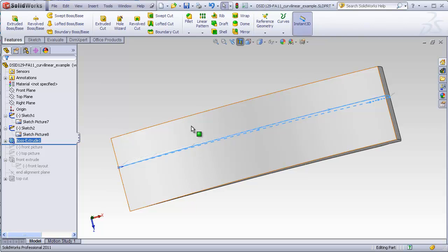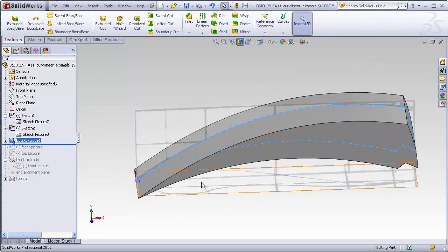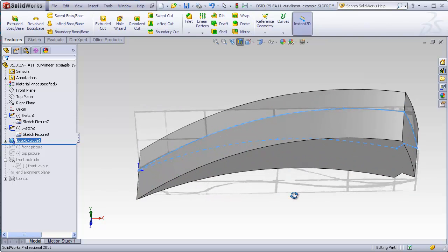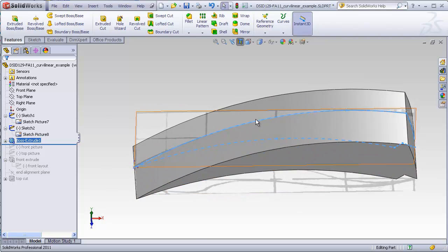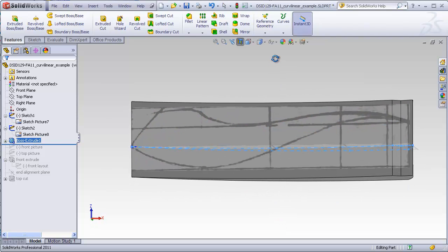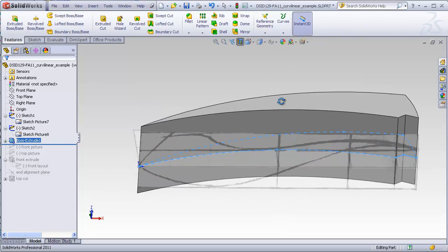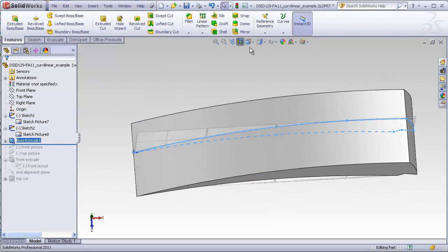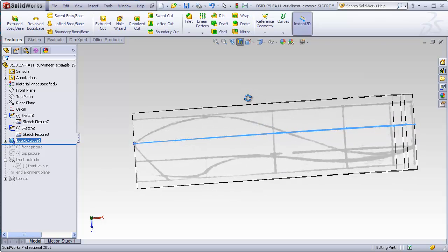As you can see, now that we've done this extrusion, we actually can't even see our JPEG image down below. So we have a couple of choices. One is to draw from below when we make our sketch, or another is just simply to go in a wireframe mode, which can be found here under Display Style, and just change to wireframe, which allows us to see